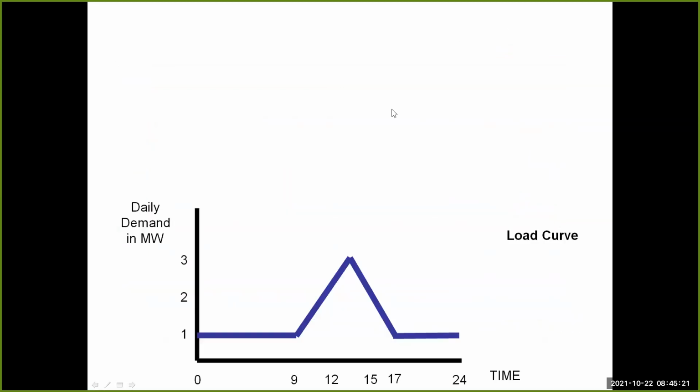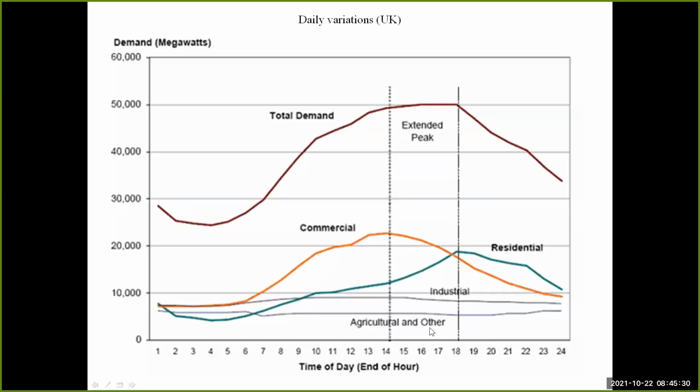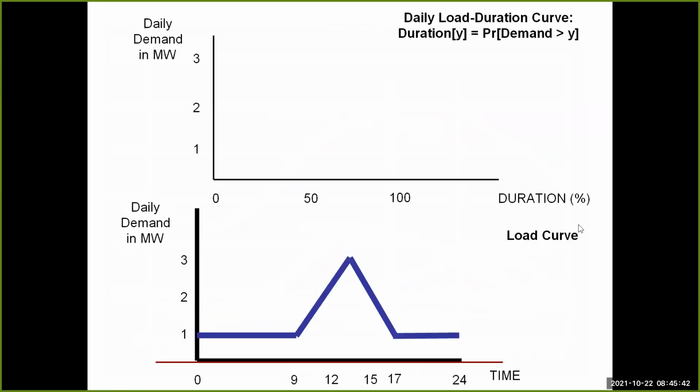Okay, let's practice it a little bit. So let's try a different kind of load curve and make the load duration curve. This is not totally unrealistic, because we really see these kinds of load curves. During the day you have low, you come to a peak, and you go down. But this is maybe a nice way to capture the basic characteristic of demand in a typical country. Okay, let us make the load duration curve. So let's see. What percentage of the time is demand bigger than, we start here at 0, bigger than 0? Well, all the time.